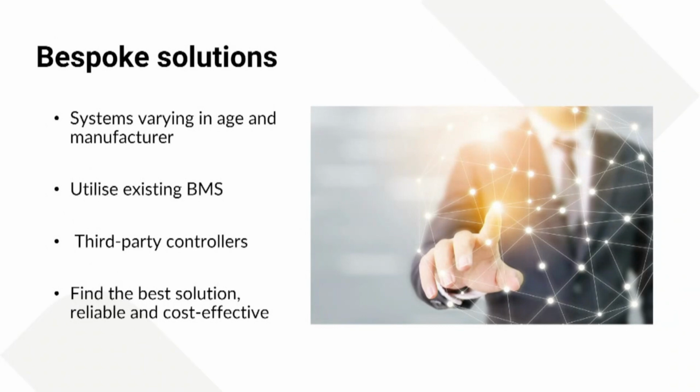So how do we export or publish BMS data to MQTT? Well, this is a system-by-system bespoke solution. The control systems vary in age and manufacturer. We utilise as much of the existing BMS as possible. And where required, we will use third-party controllers for integration. Prioritising open source, we choose the most reliable and cost-effective solution.